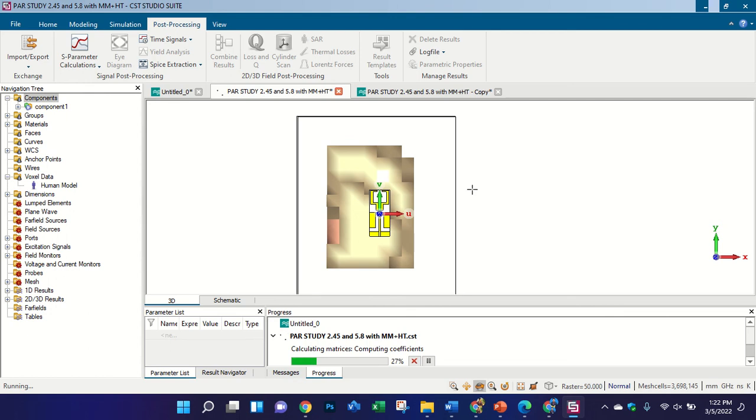No, because if your antenna is compatible, then even if you are checking your antenna on the head, on the arm, on the leg, on the chest, you will not find any big difference in the results. Okay. So that's due to the fact that the permittivities and the permeabilities are not quite different, so the results will also not quite change.